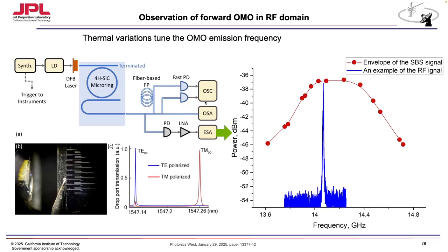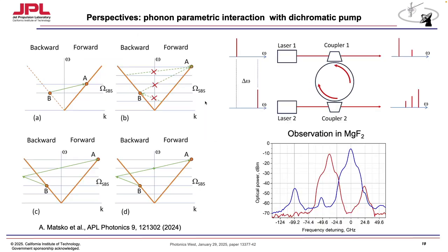It has a comparably long interaction length, so we still require phase matching conditions to be fulfilled, but it is not good enough to create a mechanical mode there. So from that perspective, the scattering resembles scattering in bulk. But since again we have a very thin film, we calculated that due to the difference between sound velocities, all sound waves that are created in the chip just go into the substrate. Still, it operates well, and this observation is very reliable.